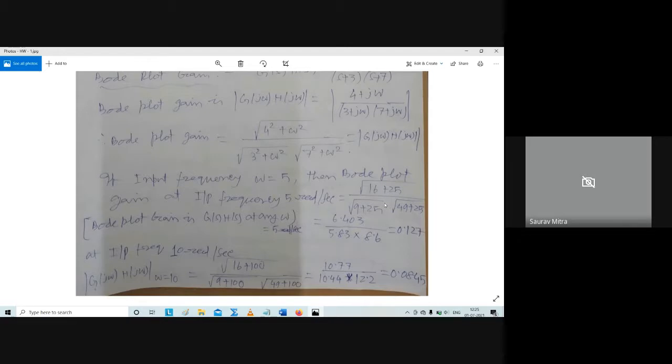You do not have to do all this in the Bode plot, nothing at all, but I am just telling you how the Bode plot is developed. So in G(jω)H(jω), the mod of that, the amplitude, always comes out positive. Whenever we convert this into dB, at that time there may be negative values. But this is not dB. Generally, the Bode plot is plotted in dB.